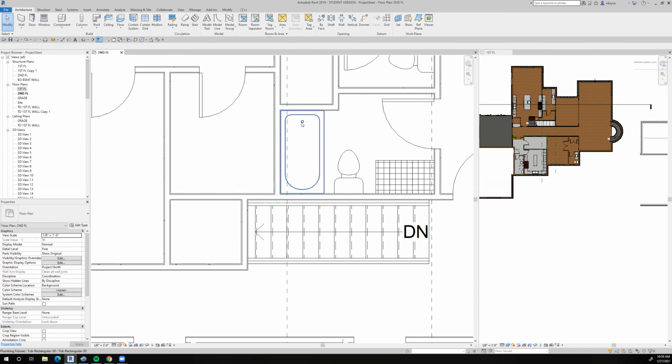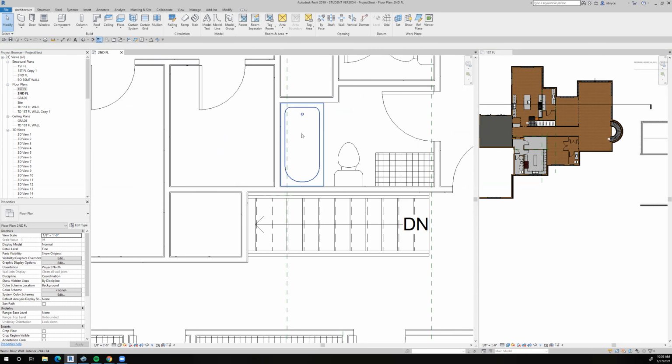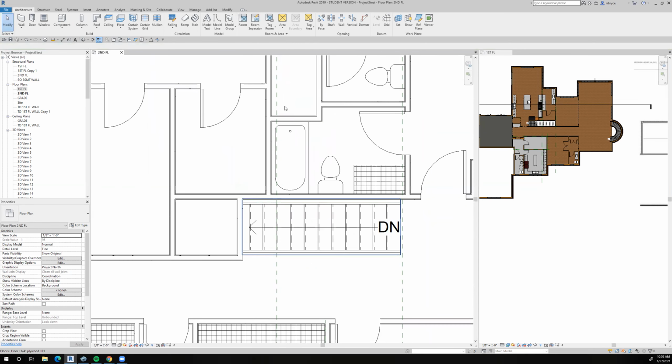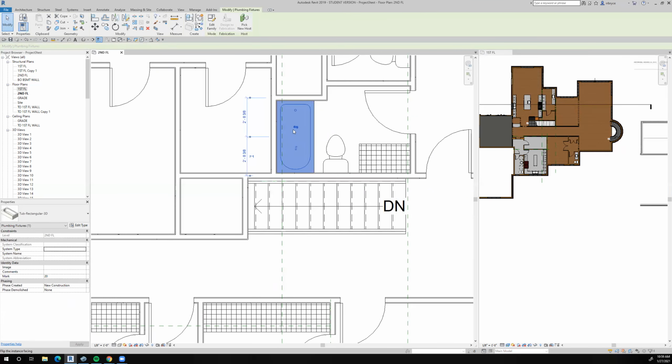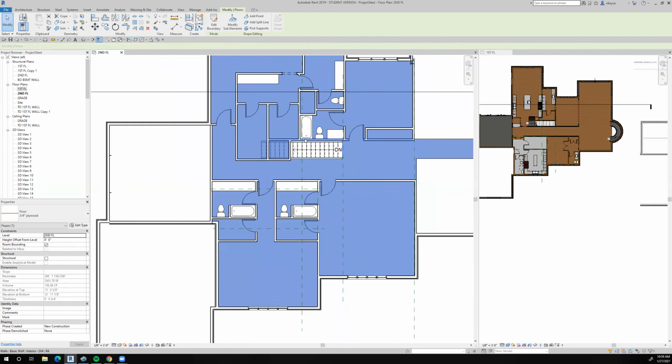This is the bathtub. The faucet, I can see that the plumbing is going to be on this wall, and we need an access panel in case anything happens, we need to access that. So I really should put the plumbing on this wall because we wouldn't be able to access it from the shower without actually breaking the tile. So let's see if I can flip that by hitting this little arrow. Now my plumbing is in the right spot. You can see that. Okay.